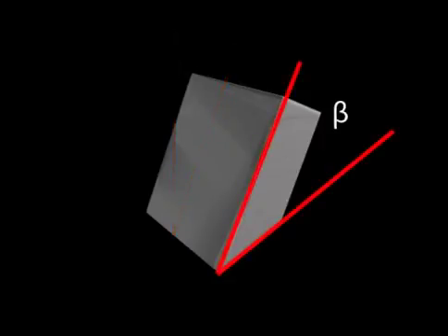The knife angle is the angle of the actual knife edge. It is largely determined by the appropriate rake angle and the required relief angle. Tools made from brittle materials such as carbide will tend to have a larger knife angle to give it higher impact resistance. Tools made from tougher materials like high-speed tool steel can have smaller, sharper angles.